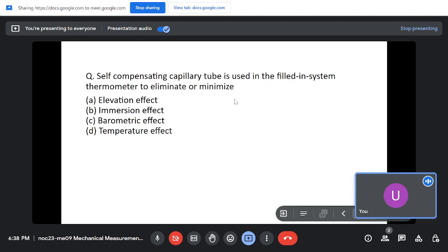So suppose a fluid is at temperature T and you want to measure the temperature; you inversely calculate it based on the pressure. That temperature will cause some increase in the pressure of the fluid in the bulb, and that increase is reflected by the meter. So using that pressure, you can estimate the temperature. But this measurement can be affected by the ambient conditions.